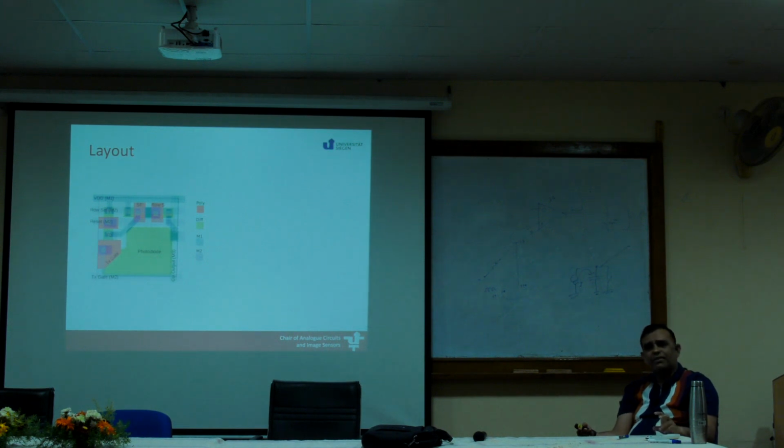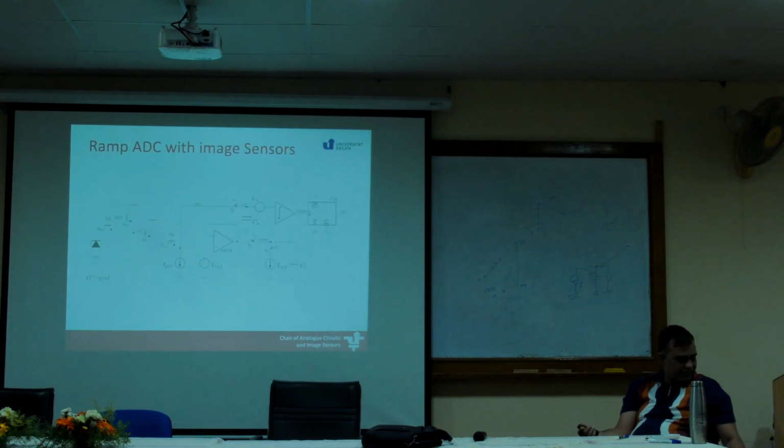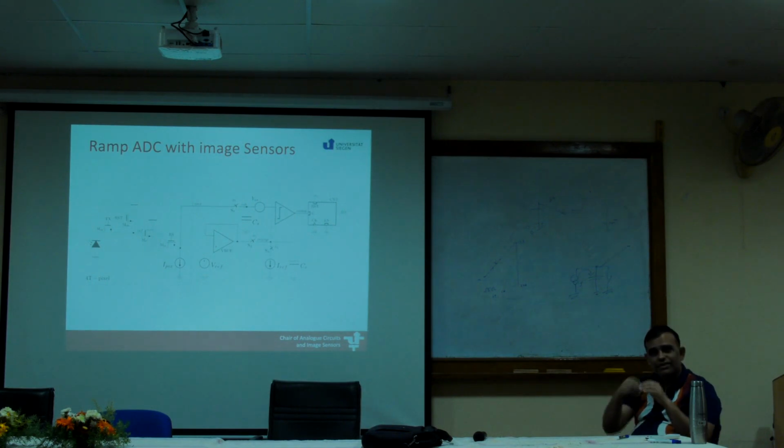The other thing which happened was our market kept on asking for more and more pixels. So we started with 4 transistors per pixel. We then asked the question, things like the reset transistor. Let me go back to my pixel. You see this reset transistor, once it switches on to reset the pixel, then it switches off. It does nothing for the rest of the time. Agreed? Even the source follower and row select is only used when I am reading the pixel out.